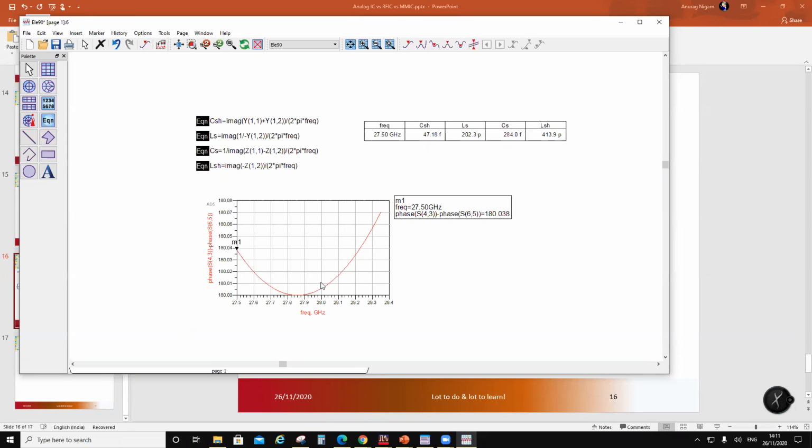So you need a low pass and a high pass element. That is why one of them is a low pass element and the other is a high pass. You cannot just accomplish this with a transmission line, because a transmission line is just a low pass element. Have I made myself clear? So you understood why I cannot just use a transmission line and a phase difference of 180, because how would you get the bandwidth then?